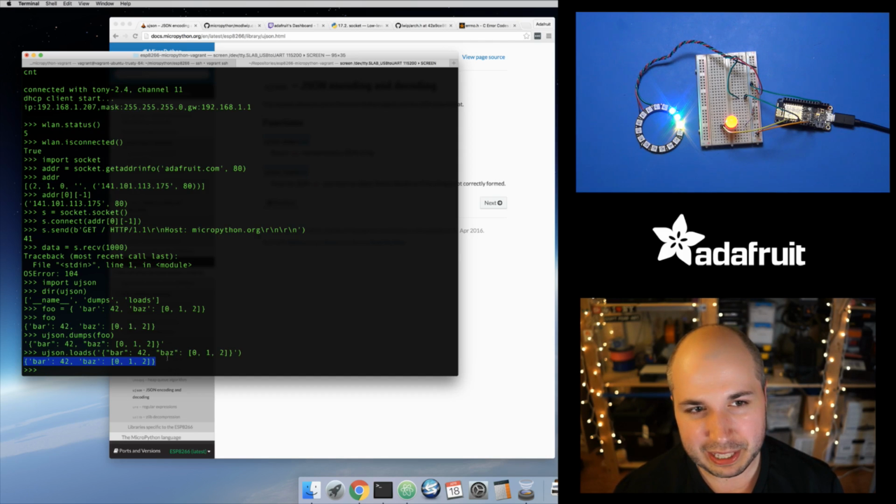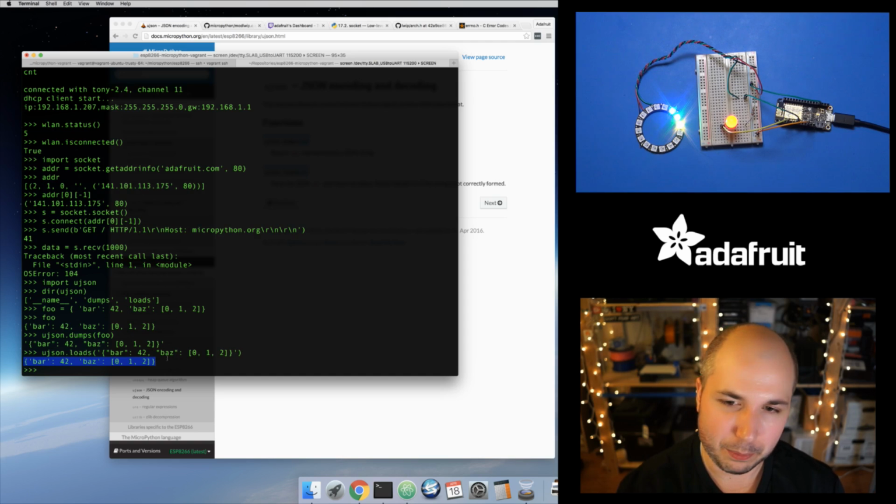And in fact, I was just thinking, the little Twitch on air sign that Lady Ada did in quite a few streams back basically has, it's using an ESP8266, but it's using the Arduino code, and it's not actually as advanced as parsing all the JSON code, because Lady Ada kind of saw that you don't actually have to parse all the code. You can actually just look for the presence of a certain value, which is the kind of trick that you usually end up doing in Arduino and C code.